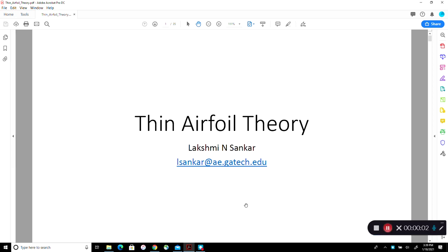In a previous video, we started talking about two-dimensional potential flows. We developed Laplace's equation for velocity potential phi and also for stream function psi. Then we looked at several building blocks, very simple solutions to Laplace's equation. Then we stitched them together to come up with more complex solutions, such as Rankine's half body, Rankine's full body, flow over a circular cylinder, and flow over a lifting cylinder.